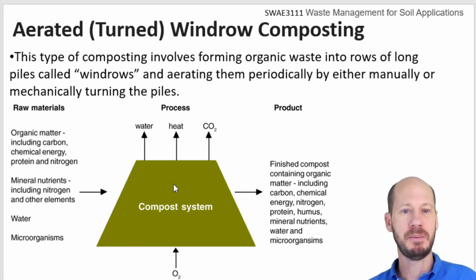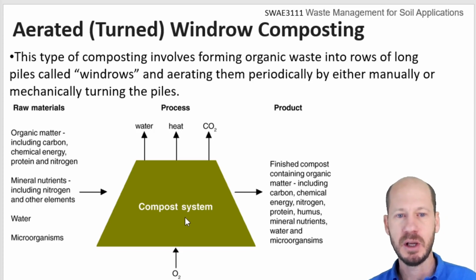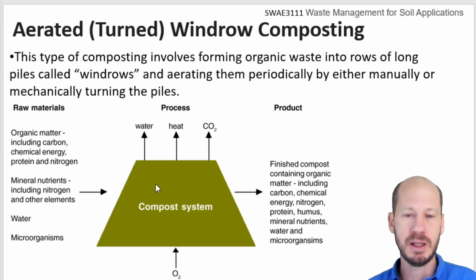In the process, the microbes will release heat and there is loss of moisture. So you need to take care of some of these parameters to optimize the oxygenation, the temperature management, and the moisture content. It must be optimized to keep this process highly efficient and performed in a short amount of time. If you do not manage this well, you will have problems. And we'll talk about these problems right now.